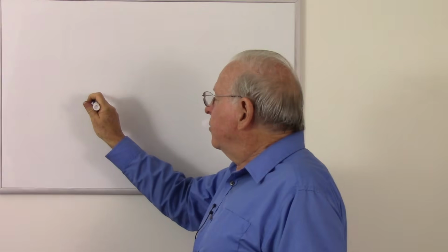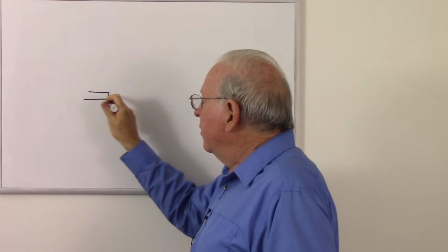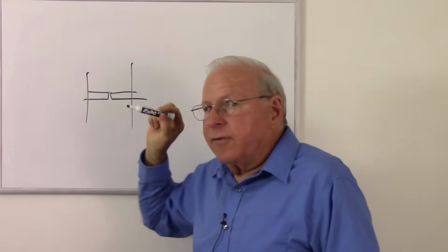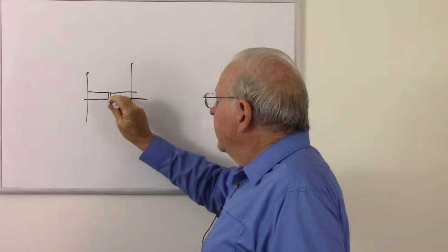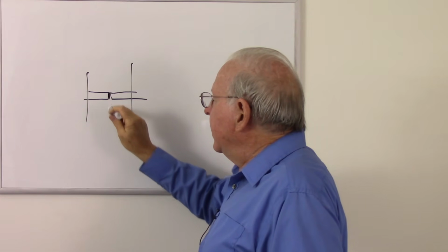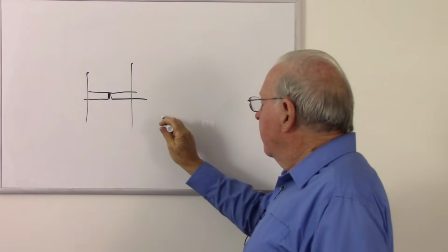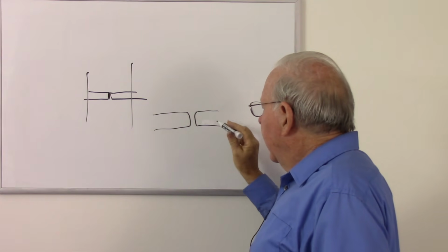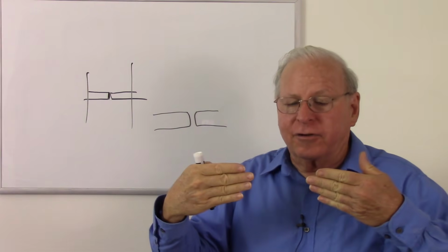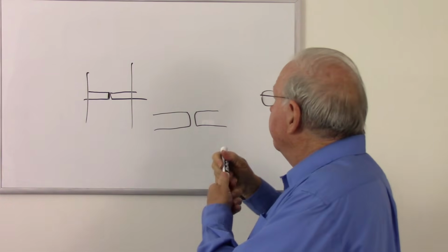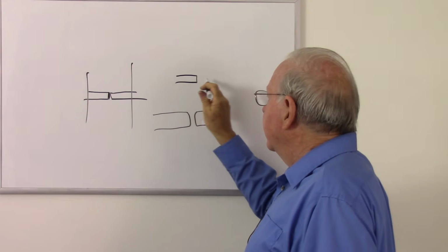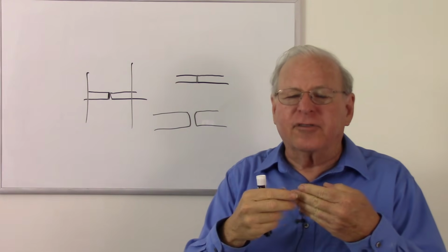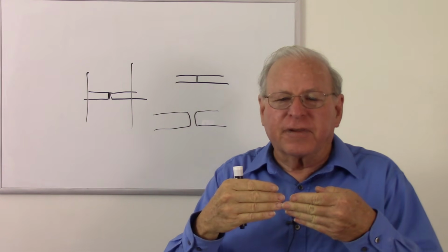So what we want to do is get two connectors together. Whenever we're connecting two fibers, whether it's two connectors, or this might be the receptacle in a switch or something, we want to get the two ferrules to connect straight to each other. And there's a little bit of a curve to it. It's getting a little scientific here, but the ferrules have a slight curve. And the idea is that the curve is just enough that, yes, there's a little bit of give. You push them together, it pushes those fibers together, and they go into what's called optical contact. This is something that happens if a surface is very highly polished. They almost become one piece of material. And so there's very, very little reflection between the two.